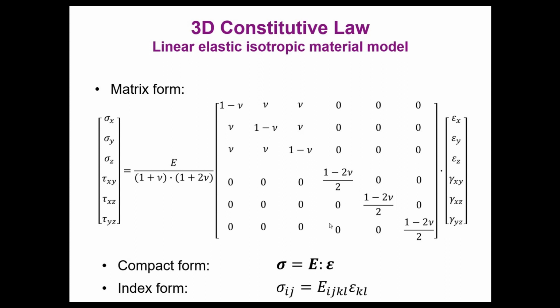So in an elastic, linear isotropic elastic model, you don't need to do that. You can work in total stresses and strains, because the relationship between these two tensors, the stresses and the strains, is linear through this other tensor in here in the middle that has only constants. But when you go to the plastic regime, your yield strength will depend on the level of strains, so you are not going to have a linear model anymore.